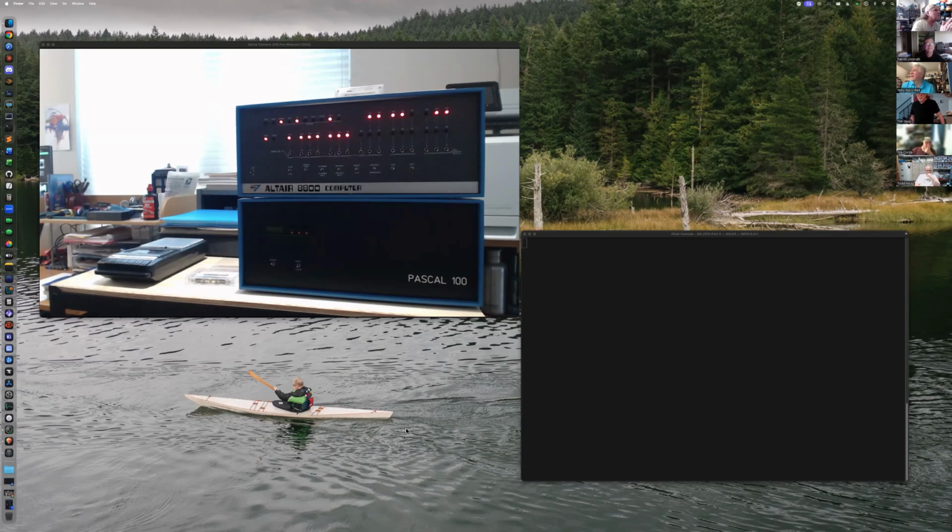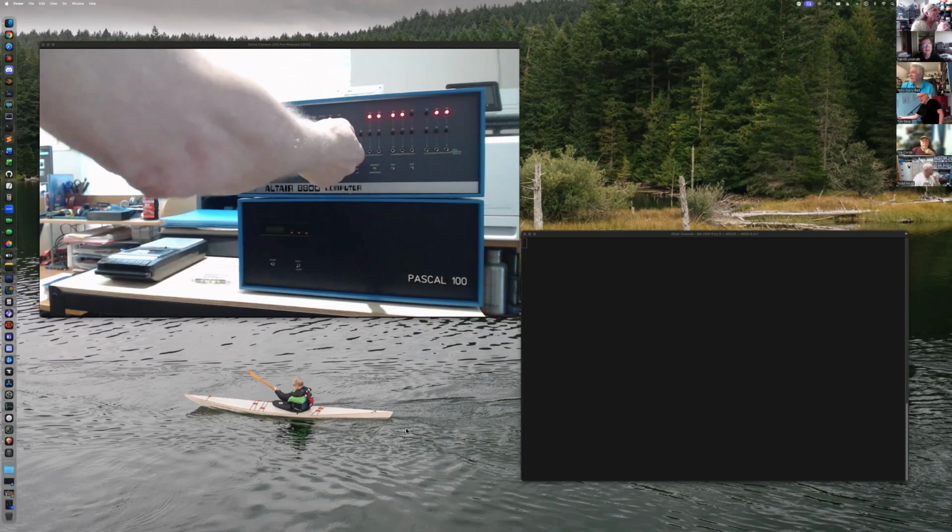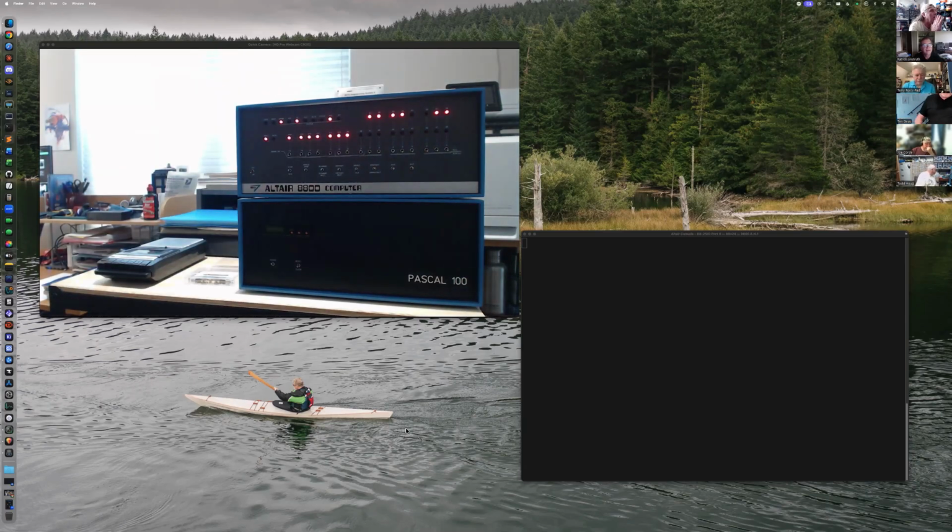Okay, wait. What switches are up and what switches are down? So everything is down except for 12 and then 8 and 9. All right. If you download the multi-boot loader manual from Mike's site, it has a list which tells you, for all of your possible cassette or paper tape sources and all of your possible consoles, where to set each group of 4 bits. The multi-boot loader will use those itself, at least it uses the cassette port itself, and then it will also tell BASIC, so BASIC comes up on the right port and understands where the cassette is, so it passes that information off.